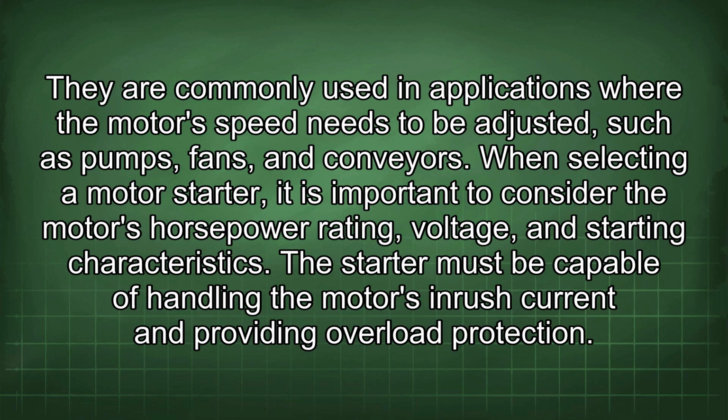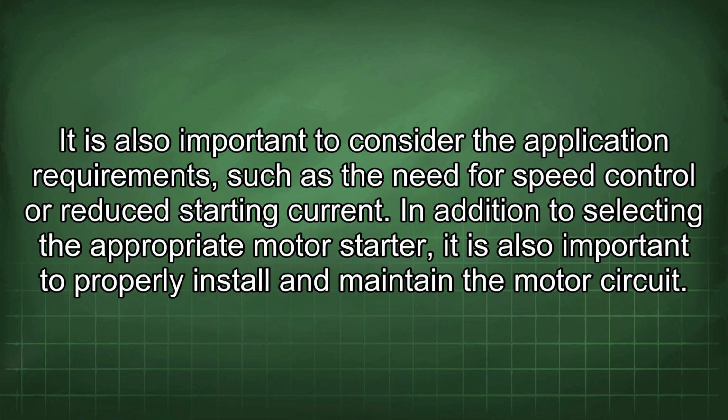When selecting a motor starter, it is important to consider the motor's horsepower rating, voltage, and starting characteristics. The starter must be capable of handling the motor's inrush current and providing overload protection. It is also important to consider the application requirements, such as the need for speed control or reduced starting current.